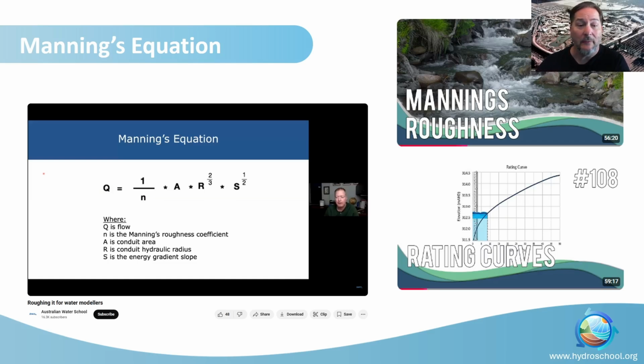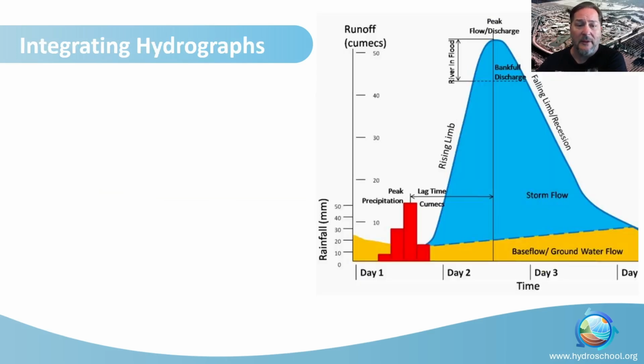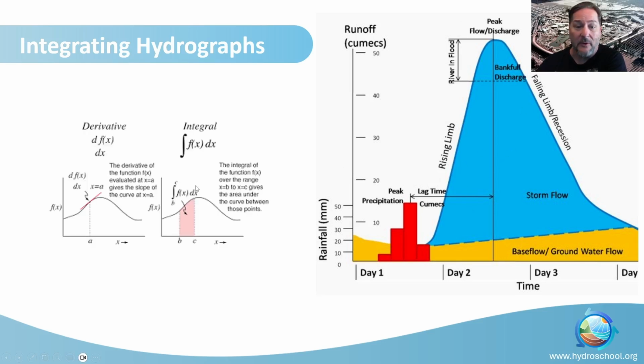So in the same way, if we put steady flow into a 1D model, it's as if that's been running at that rate forever and ever, and it'll just fill any storage volume instantaneously. So to nail down that concept, I think we need to recognize that the area under the curve of a hydrograph represents a volume of water.